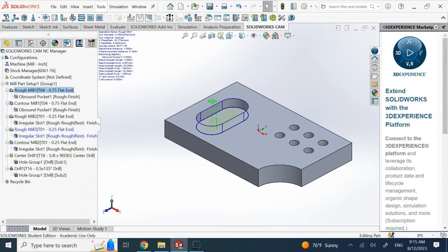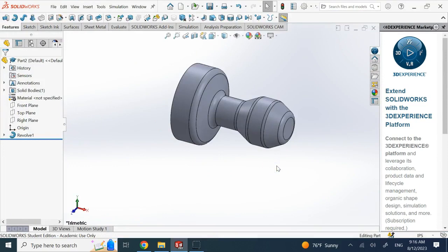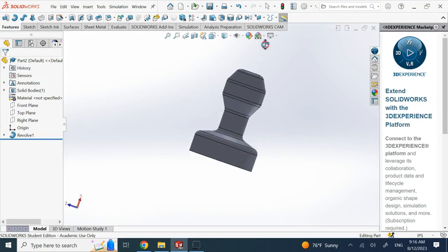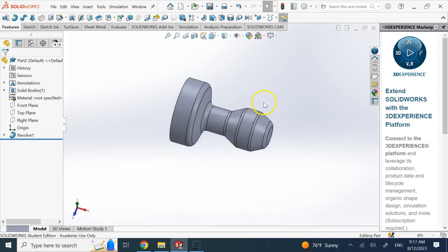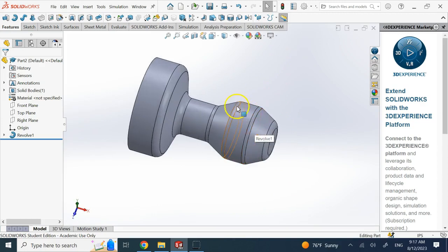For the next example, I want to show you a simple lathe operation, or spinning axis only. Let's say this is a rough pawn in chess. One of the things you see is I'm using a fillet here and trying to avoid sharp internal edges, not only for stress concentration but also for machining. You'll see it might not even be able to do a perfect simple lathe operation on that, depending on how sharply you are changing the angles.